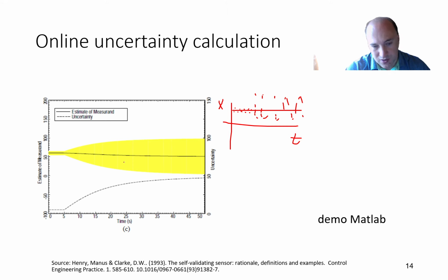So in a chart it looks like this. You have some measured value and some interval where with a reasonable probability you expect that the data is correct. And you can see that we're basically again looking for the width of some interval. So what we will do is to set some threshold. We'll say if uncertainty is, for example, in this interval like that, then it's okay. But now we are outside of this interval, and then from this time on we will use a logic signal and we'll say that this is an error and that we should do something. So this method is not able to correct the problem, but it's at least able to tell you that there's something wrong with the signal.